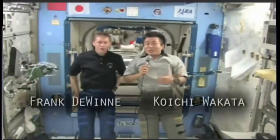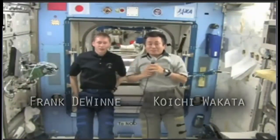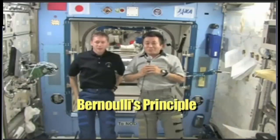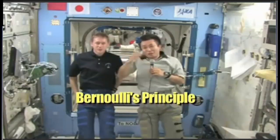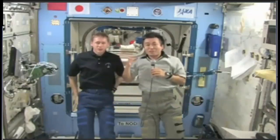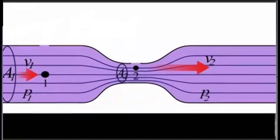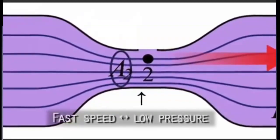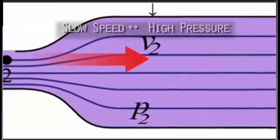In a fluid flow, when the flow gets higher, the pressure decreases. And this fact is now well known as the Bernoulli principle. If you apply this principle in a fluid flow, in a closed system such as water flow in a tube, if you imagine the tube gets bigger and narrower, the pressure actually decreases when the speed gets higher. And when the speed of the water gets slower, the pressure actually increases.